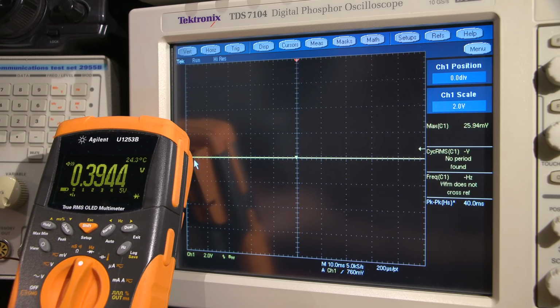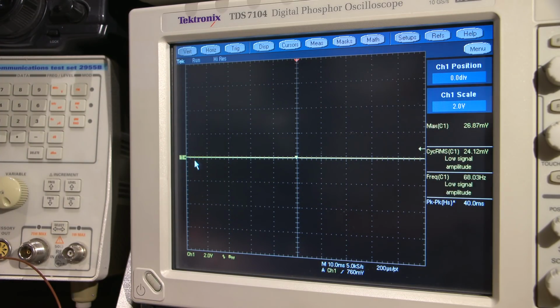So now we know that the line side of the diode, the cathode side, is face up. So the line side of the diode attaches directly to test point number 8, and we also know, because of the low forward voltage here, 0.394, that this is a Schottky diode. So right there, this is telling us that it is not a standard diode, because a standard diode usually has about 0.6 to 0.7 of a volt forward, okay? And that would also tell us right there that this is not a Zener diode. So we verified a whole bunch of things just with a standard diode test and with some recognition. So I'll get this off the bench now. So now